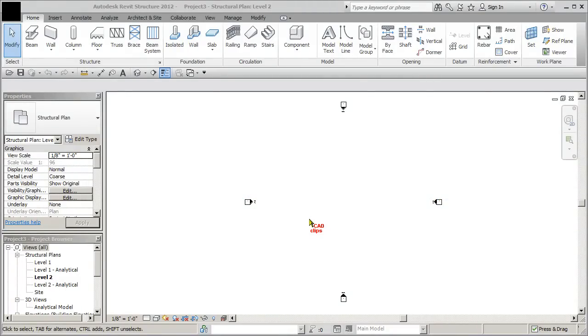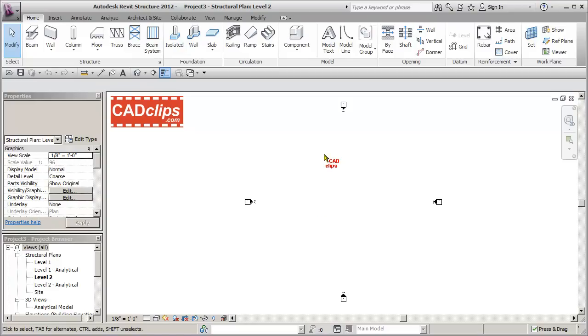In this video, we'll show you how to create a gray shaded pattern for our structural walls so that we don't have the concrete hatch pattern, and we'll put some rebar. So we'll have a structural wall with rebar and a shaded gray hatch pattern across that, and we're going to use materials. I'm just in the default Imperial template file, Revit Structure 2012.